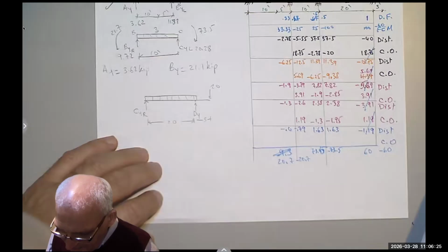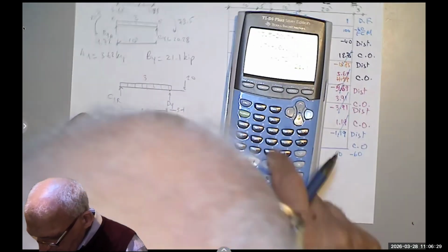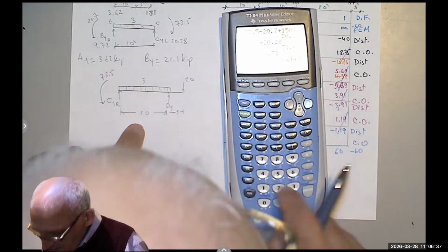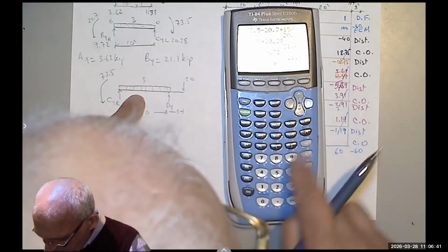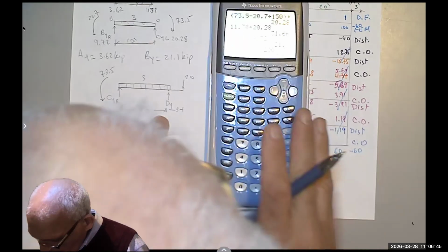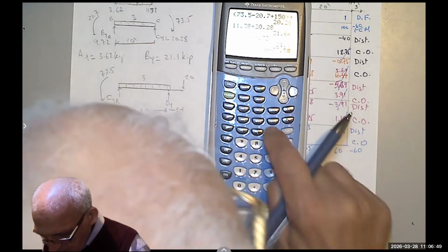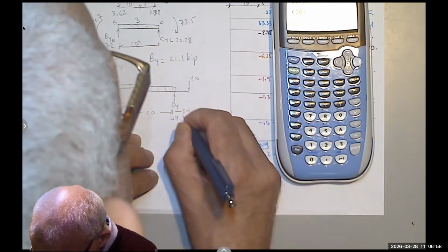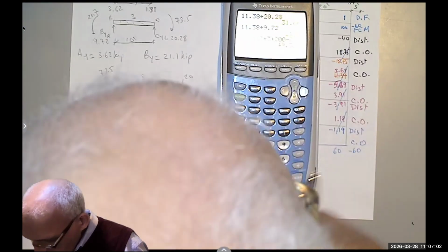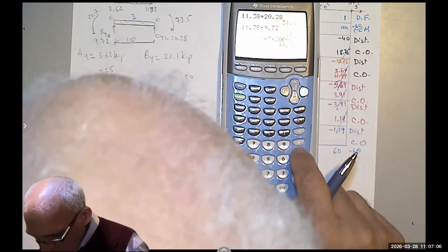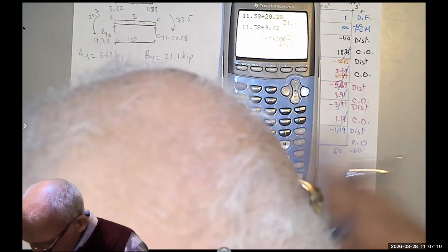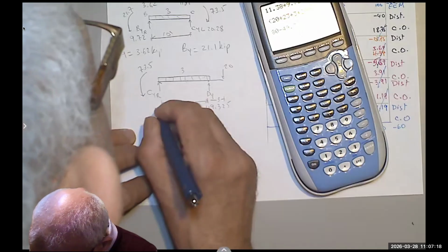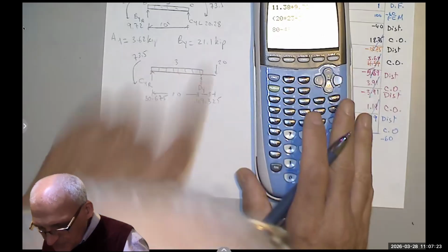So like we did before, I'm going to open parentheses and say the moment produced, oh, and the moment here, 73.5. So 20 times 23 plus 3 times 20 times 10, so 200, minus 73.5, divided by 20 to get the DY. 49.325, 49.325. The sum of this is 80, right? Yeah, 3 times 20 plus 20, minus the 49, so I get 30.675, 30.675.